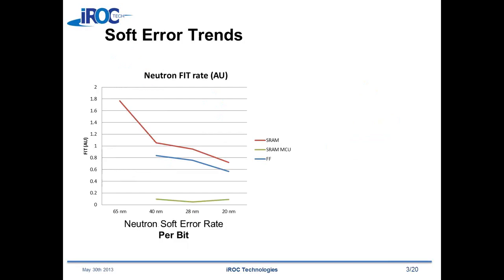That's a good question. So if we look at the soft error rate per bit, it is trending down with smaller and finer technology nodes. Part of that is just caused by the fact that the area occupied by a flip-flop or a memory cell is that much smaller, so the target is that much smaller to get hit. And also we're seeing that with the transition to new FinFET transistors, generally they're less sensitive to soft errors.